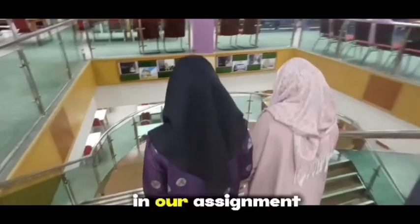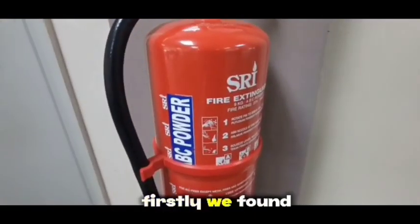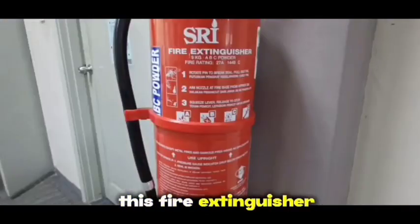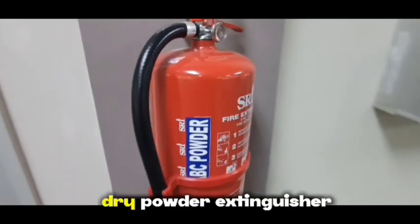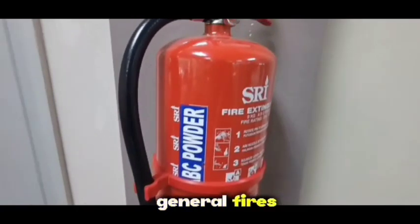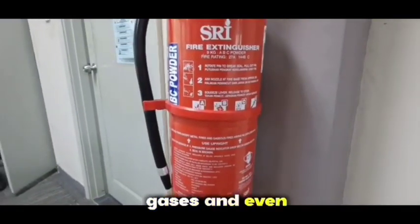In our assignment building, we found several components in the firefighting system. Firstly, we found a fire extinguisher. The type of this fire extinguisher is dry powder. Dry powder extinguishers are usually used for general fires such as solids, liquids, gases, and even electrical equipment.